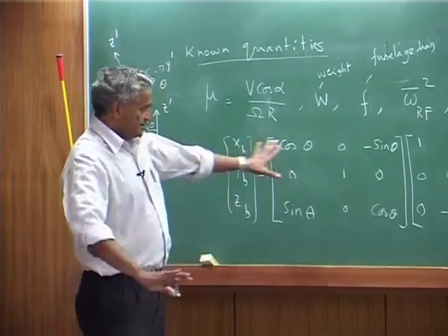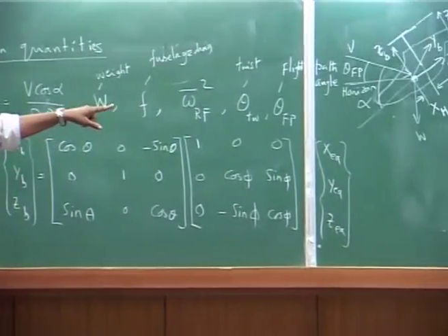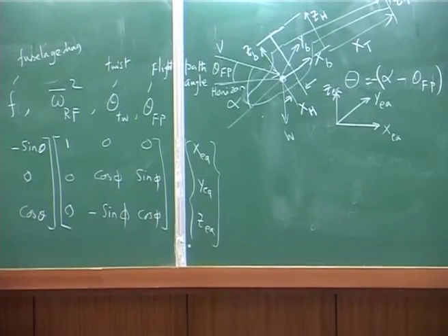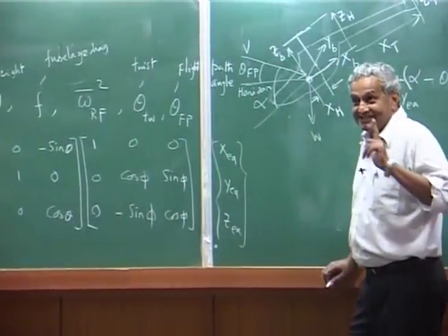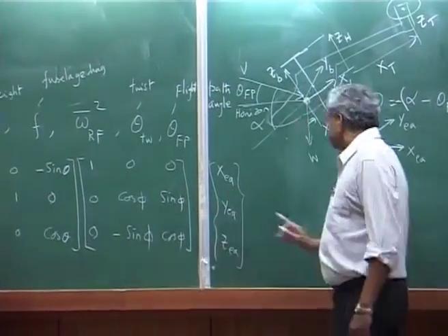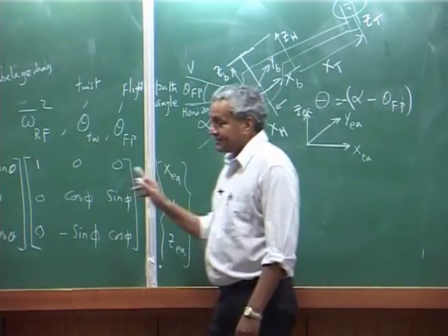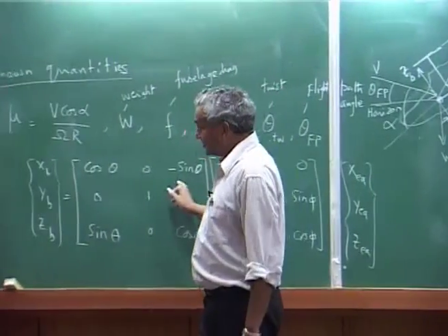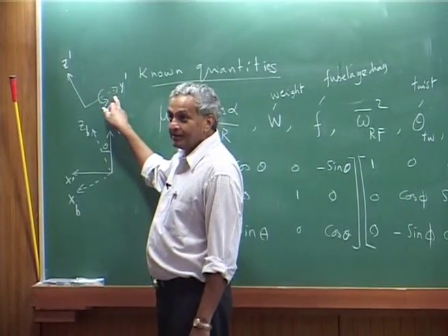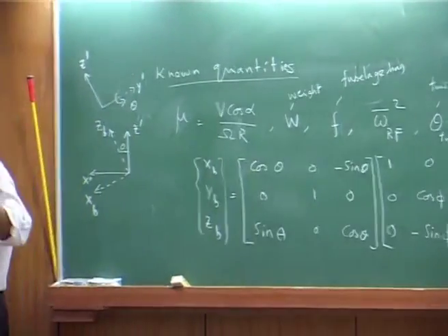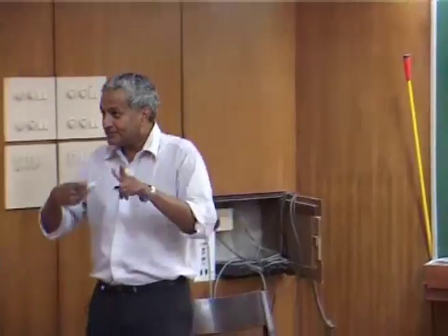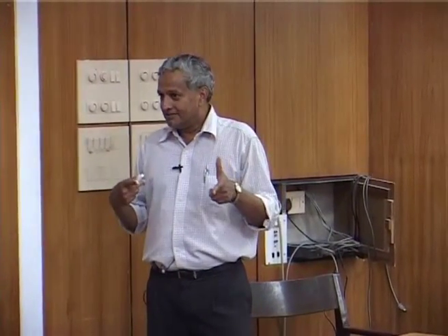Now you got this, the only thing is for theta you have to put a minus sign, because as per the diagram, that is the key. Now please understand that phi is rotated about the earth axis, whereas theta is not rotated about the earth axis, theta is rotated about the rotated axis. It is not about the fixed axis system that you are doing the rotation. So every rotation is about the rotated axis, after you get a new position about which you rotate. This is the sequence you follow.